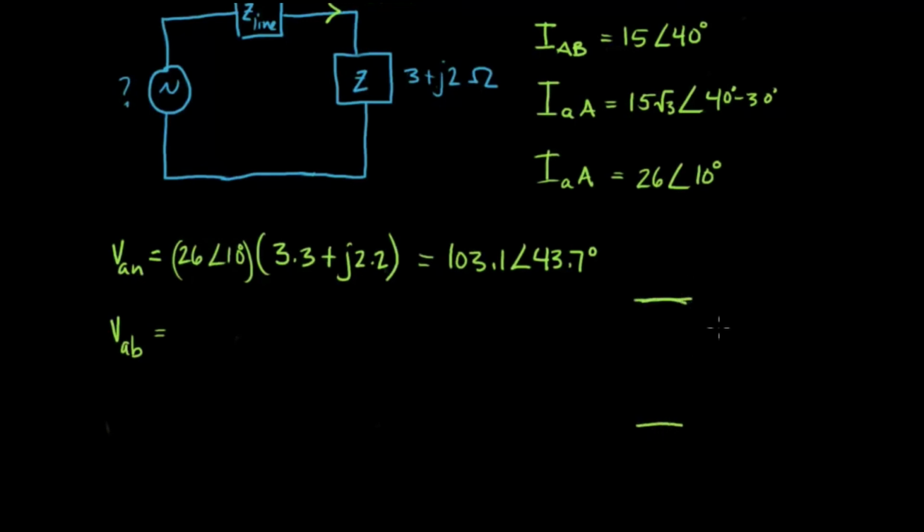And the voltage between those lines is given by either a delta or a Y network. If it was a Y network, there'd be two batteries, parts of two voltage sources across those lines. If it was a delta, there'd be only a single one. So the delta one would have to be larger in order to match the voltages of the two independent sources.